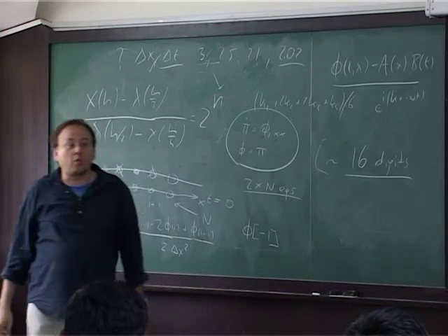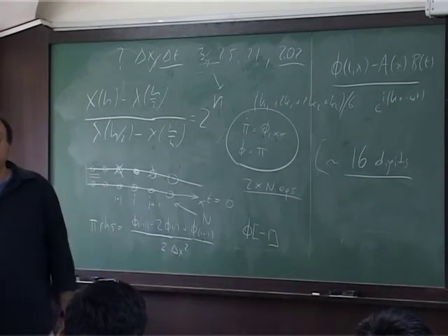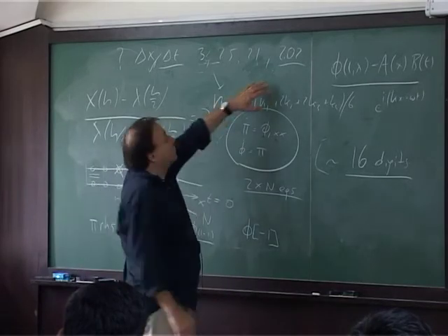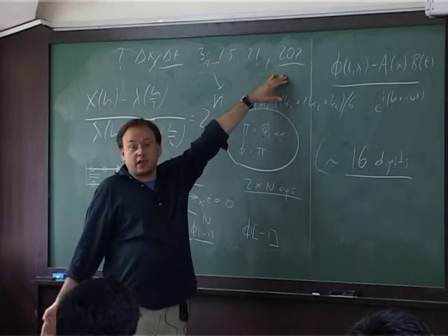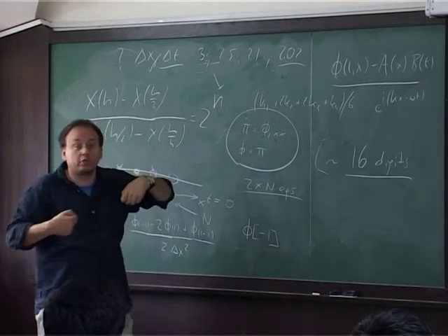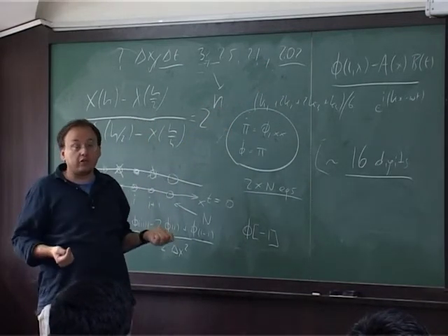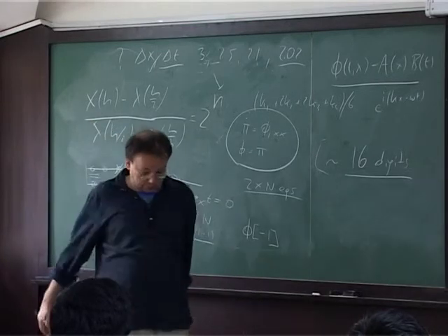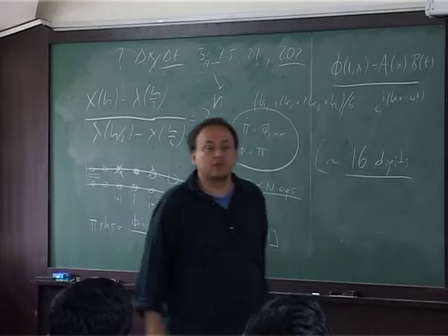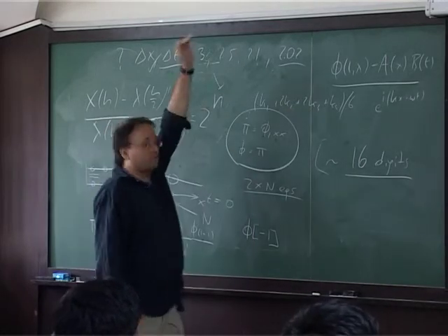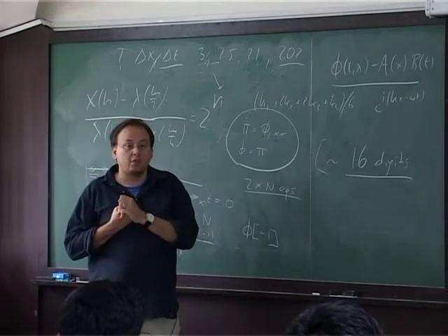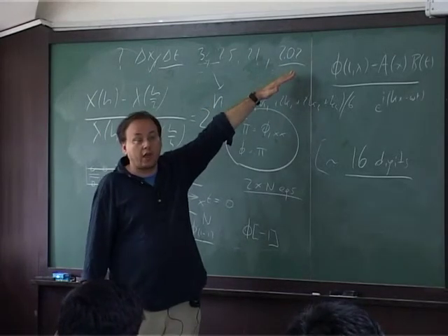At this point it's perfectly consistent, and spending any more computer or human time on the convergence test is pointless. If the error is not yet good enough because an experimenter needs 8 digits, well, refine further until you have the accuracy you need. But for the purpose of the convergence test, you're okay.